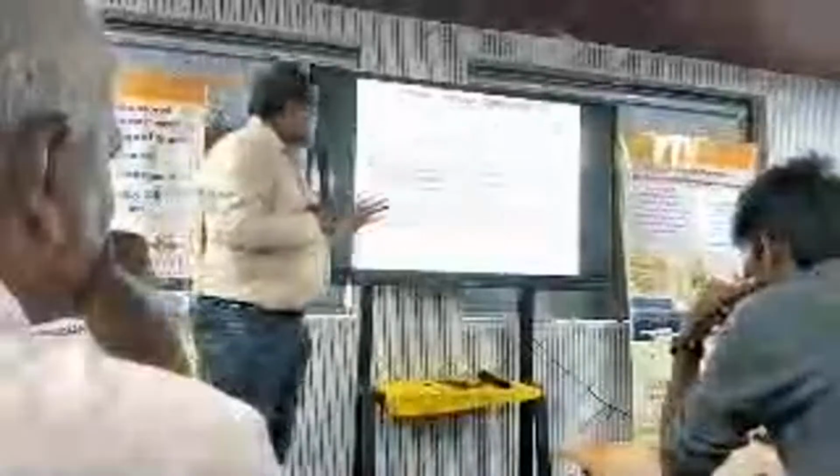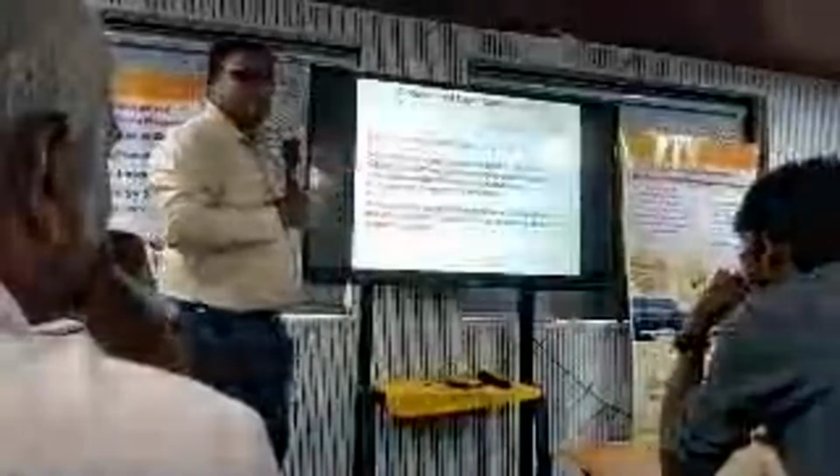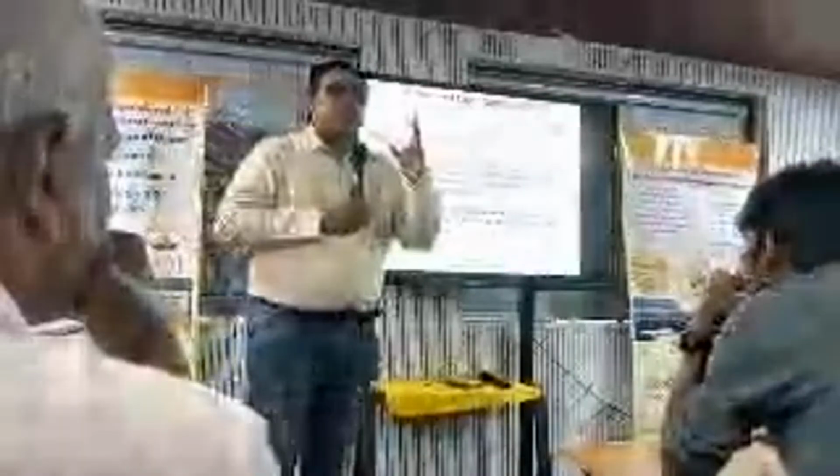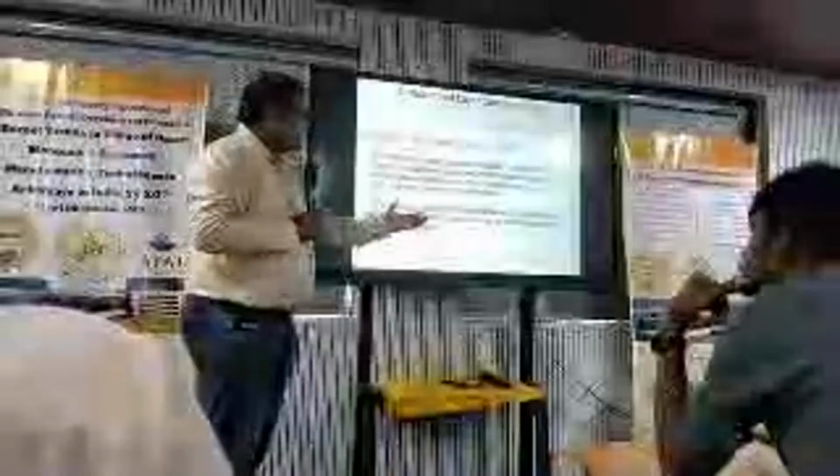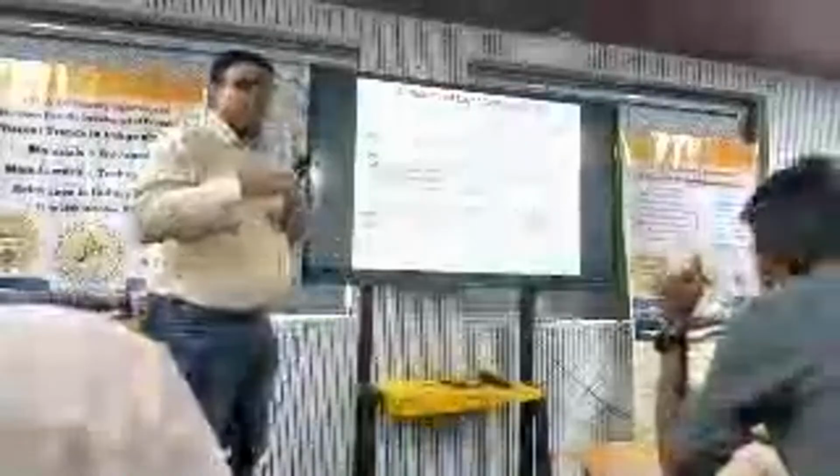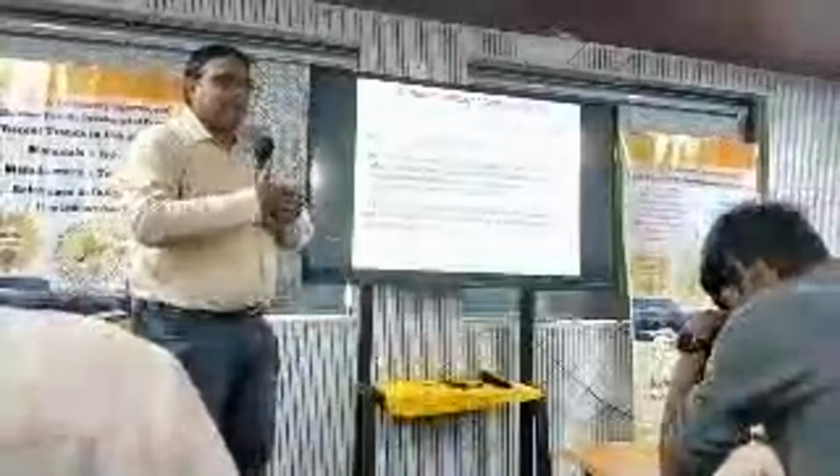And this is the CLD, constrained layer damping treatment. This has 3 layers. Previously FLD had only a 2-layer structure, the extension damping. And this is the RKU equation, which consists of 3 layers: the base layer, the viscous rubber layer, as well as the metallic substrate again. These 3 layers will be there, and the conversion is mainly because of shear deformation. Shear from one layer to another layer, because of the shear stress, is how the energy transfer takes place.